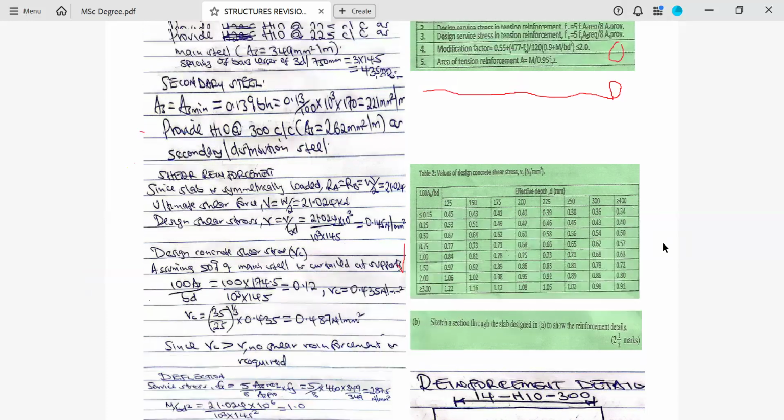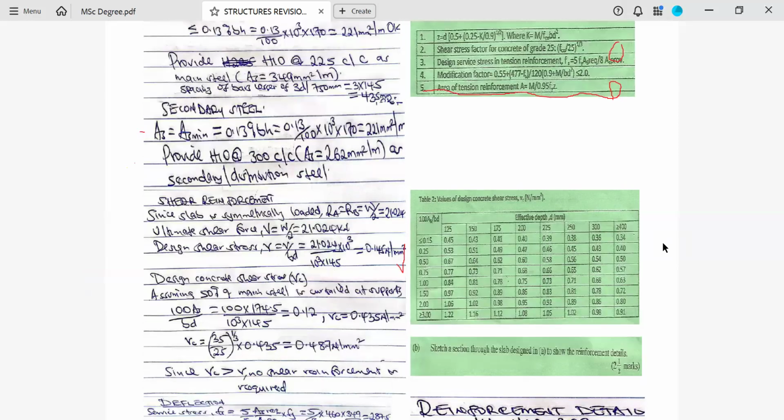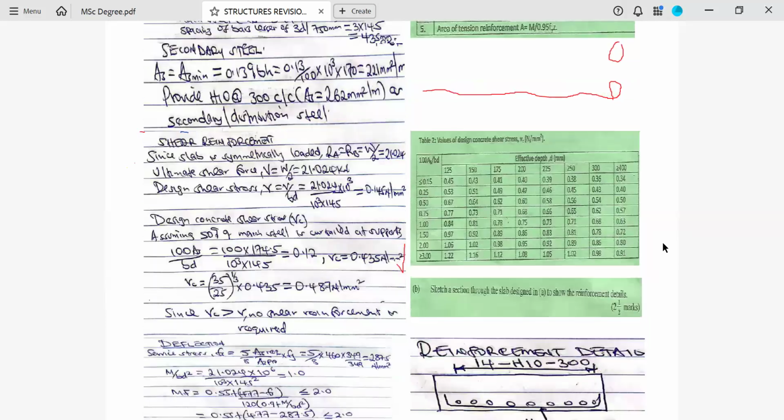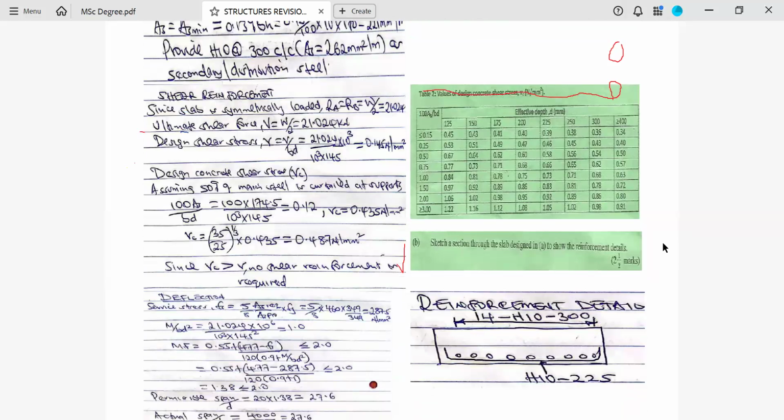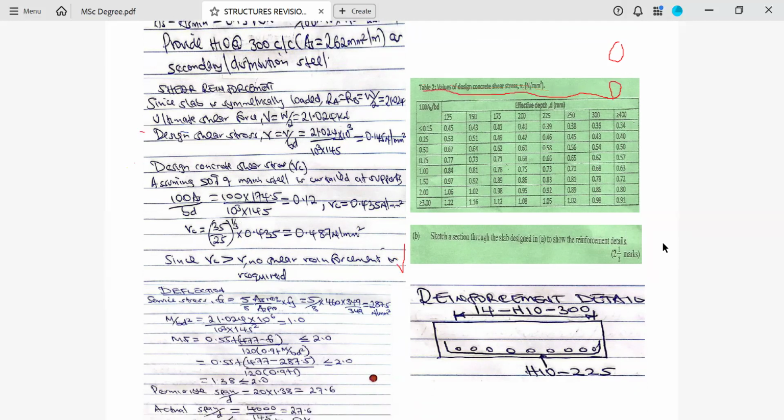So we had, maybe to clarify, remember area provided was 349, but this 349 is in form of reinforcement bars. And now, remember one bar reaches the end, the next doesn't reach. It reaches the opposite end, meaning that only 50% of the bars reach each end. That's why we divide the value by 2 to get 174.5, divided by b is 1000, d 145, which is 0.12.